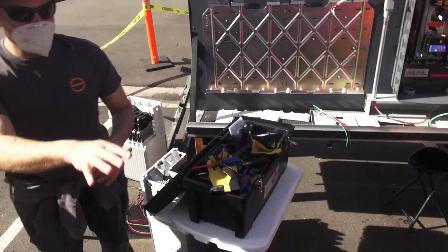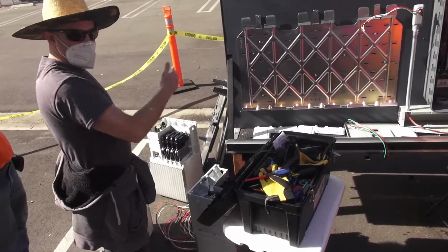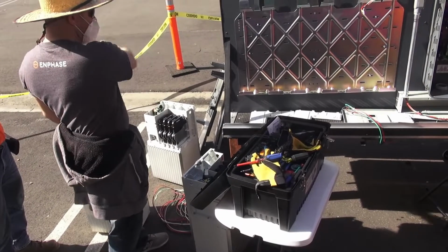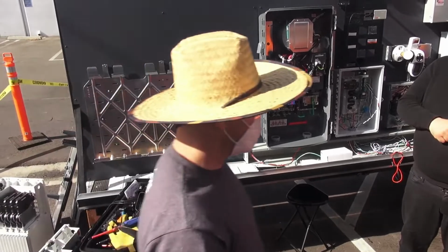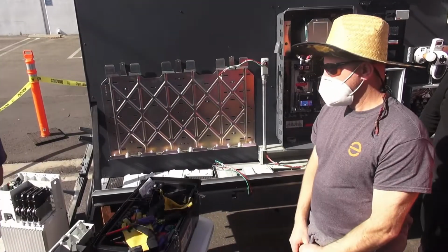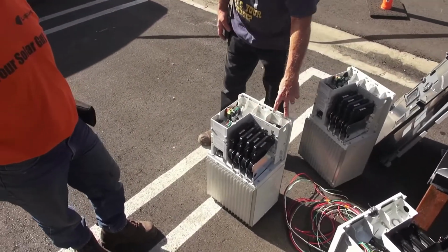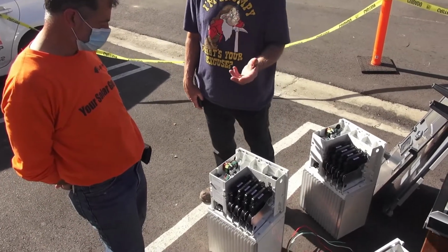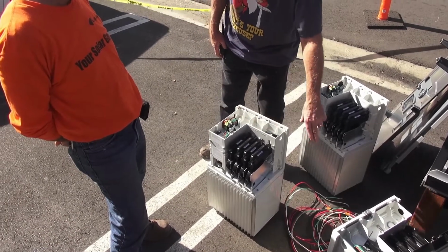And the reason why I'm a little torn about it is when we do these 3 together, that's what we're doing. We're linking those 3. So it's like, why is it a big deal if I have 4, 5, and 6? I admit that. If you've got the room to put the junction box in, put the junction box in. Because technically, this is just a trough. It does have boxes, but it's not designed for that. It's not in the specifications to use. This is not known as a junction box. This is just a wiring path.